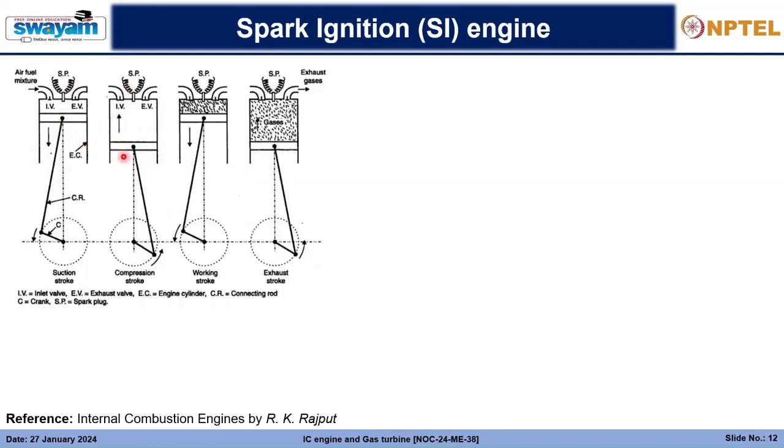So you will see four times this piston is moving up and down, right? This is one stroke coming down from the top dead center to the bottom dead center. The top dead and the bottom dead center basically signify from which point to which point the piston will move. When the piston moves from top dead to bottom dead and again comes up, again goes down and again comes up, it is executing the stroke four times, and accordingly it is a four-stroke engine.